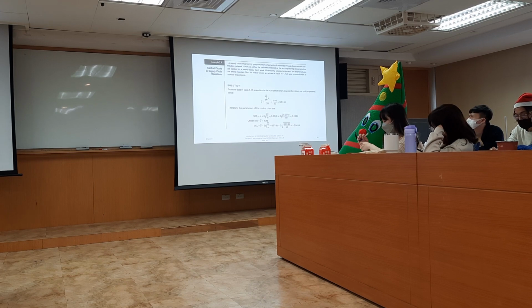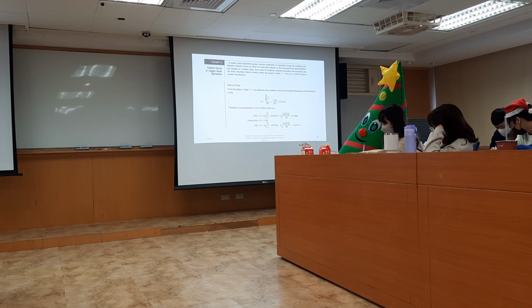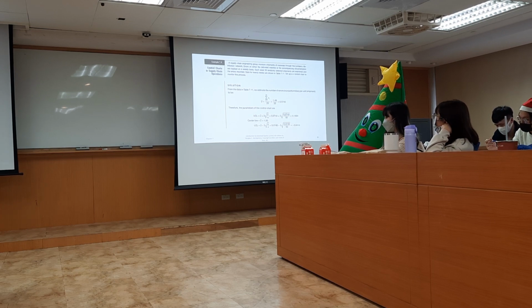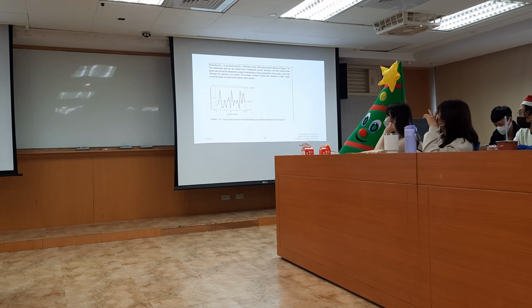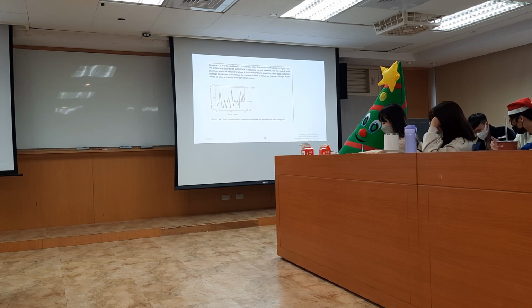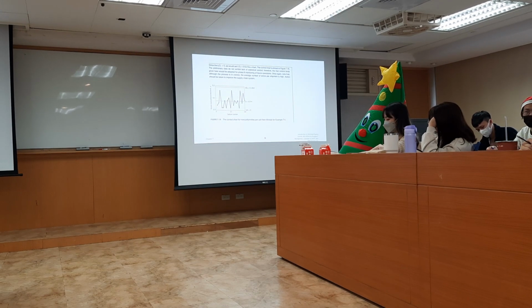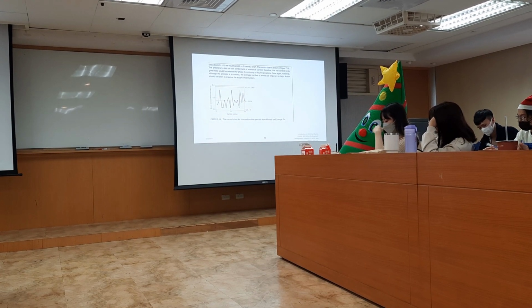Like this is 0.1894, and this is negative. However, there's no sense to this; the number cannot be negative. So we should set it back to 0. Since the lower control limit is less than 0, we set it back to 0 for the u chart.